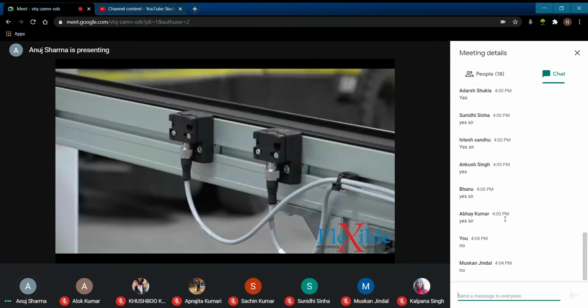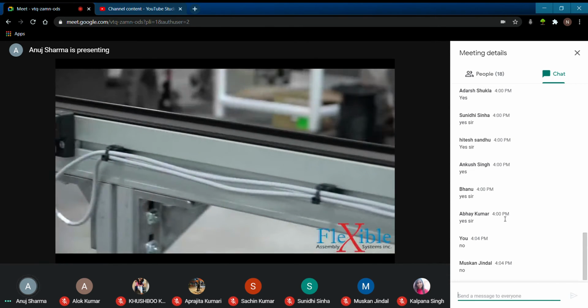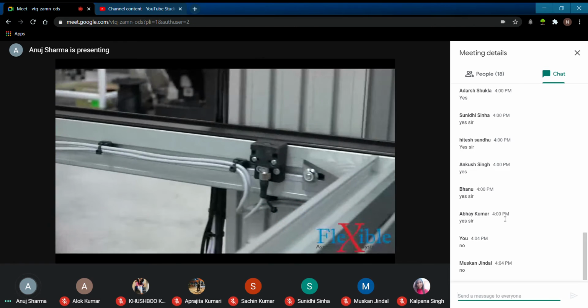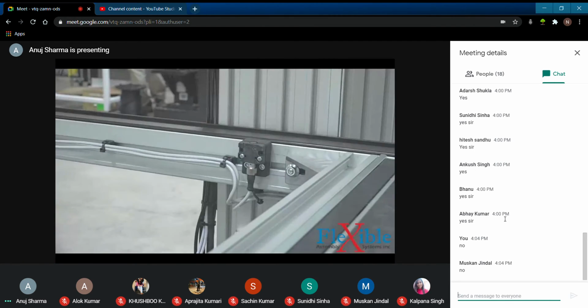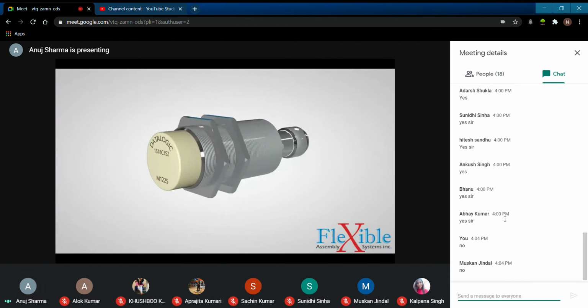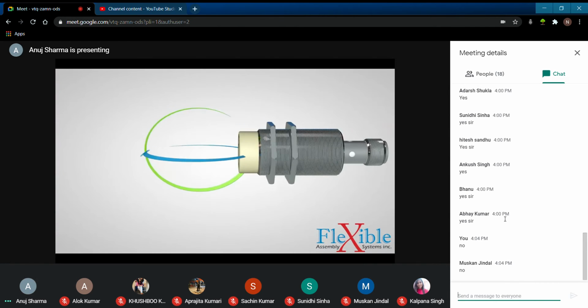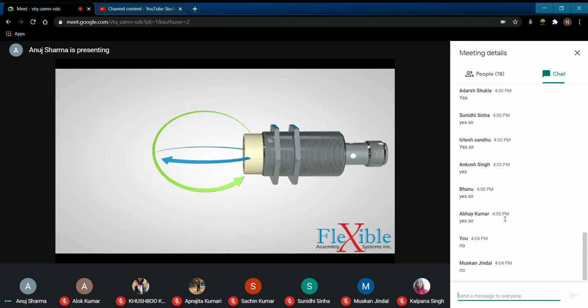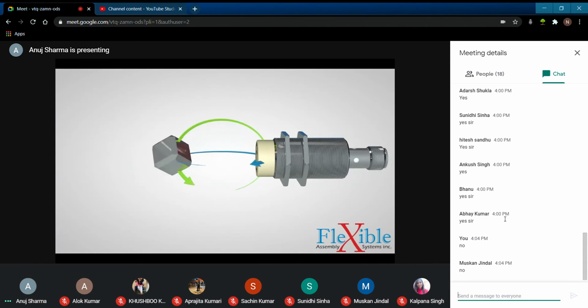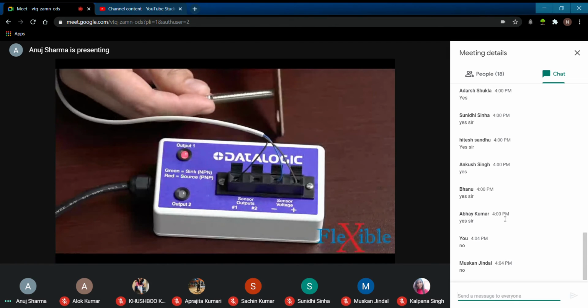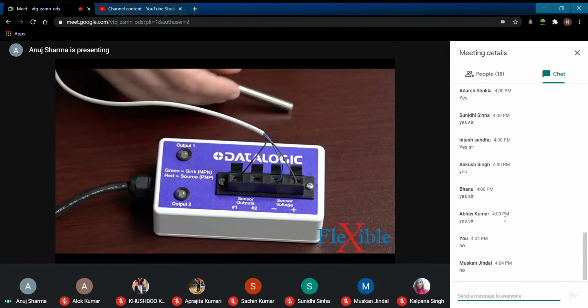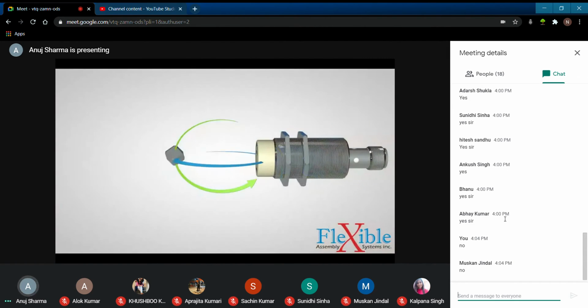In automation, they are regularly used to sense the presence of a metal part and send that information to a programmable logic controller. An inductive sensor is a non-contact sensor that uses a coil and an oscillator to generate a magnetic field around the sensing surface. When a metallic object enters the operating area of the sensor, there is a dampening of the oscillation amplitude, which is read by a threshold circuit and changes the output. Any object that isn't metallic won't interfere with the magnetic field that is generated around the sensing surface.